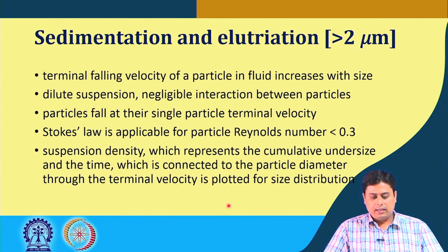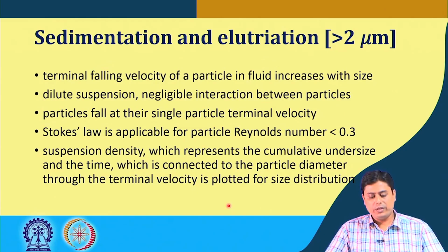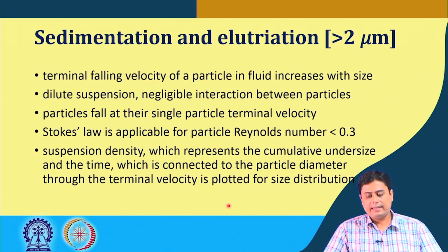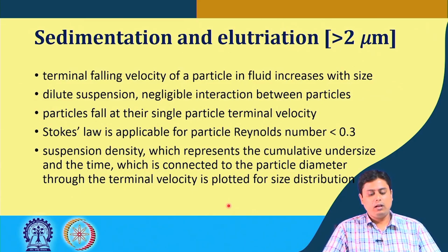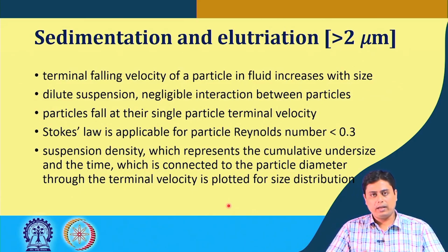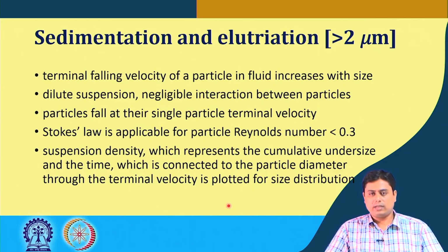In this technique, based on that fact, we typically apply Stokes' law, which is applicable for a particle Reynolds number of less than 0.3. And also, if you may remember, Stokes' law is applicable for low Reynolds number cases, and it is applicable for dilute suspensions, where there is negligible interaction between the particles.